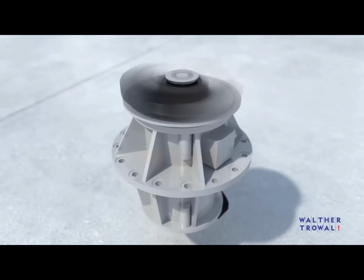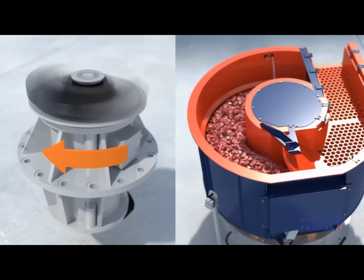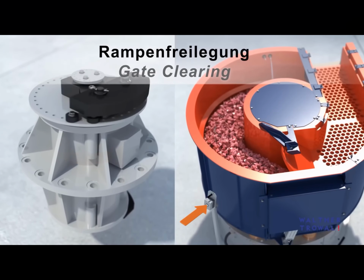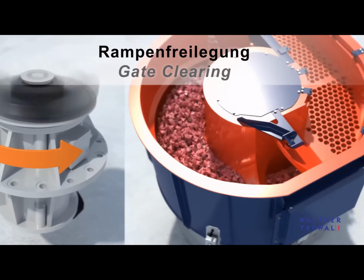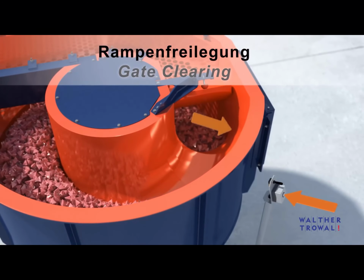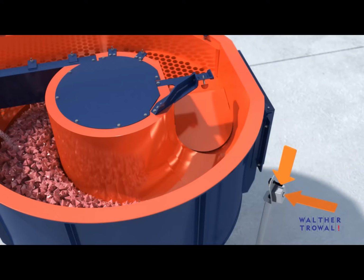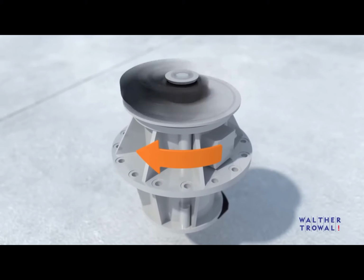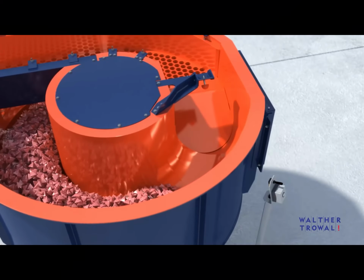The characteristic tumbling motion of the processing bowl is controlled by the quantity and setting of the imbalanced weights on the vibratory motor. Pushing and holding the button changes the motor's rotational direction and clears the ramp area of any media and workpieces. Clearing of the ramp area ensures that no workpieces or media get caught by the separation flap when it is lowered onto the ramp. When the button is released, the rotational direction of the motor changes back, allowing the mix of media and workpieces to rise to the screen deck level.